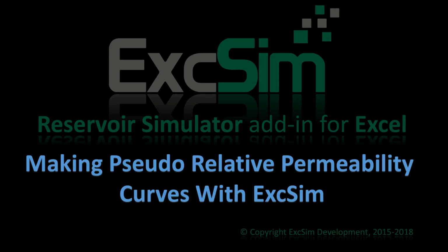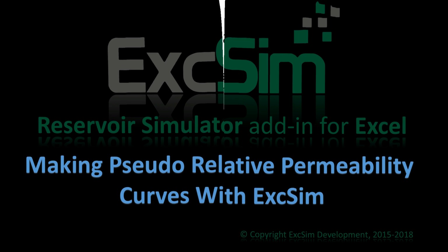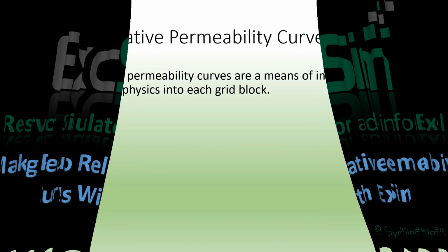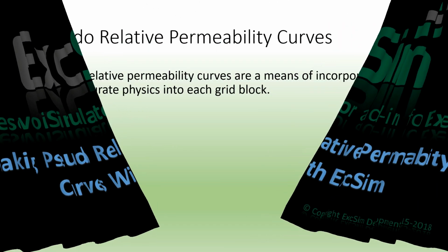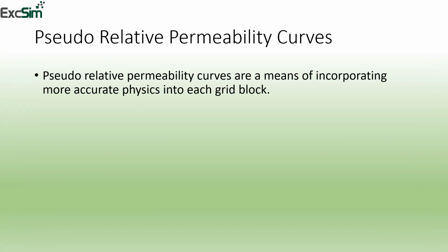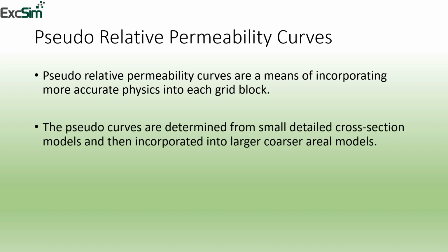In this video, we're going to show you how to make pseudo-relative permeability curves with ExcSim. Pseudo-relative permeability curves are a means of incorporating more accurate physics into each grid block. The pseudo curves are determined from the small, detailed cross-section models and then incorporated into larger, coarser areal models.